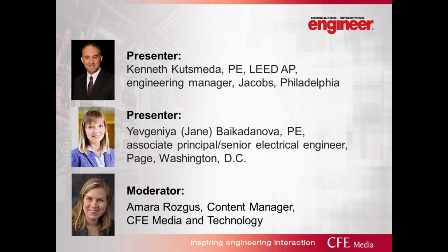We installed a step-up transformer and stepped it up from 5 kV to 35 kV and backfed their 35 kV loop to use it to back up the generators or back up the buildings. So that's an option. There are medium voltage UPSs out there that you can use to back up medium voltage systems. And again, parallel generator plants are usually tied into the medium voltage system, so that's how you would do it.